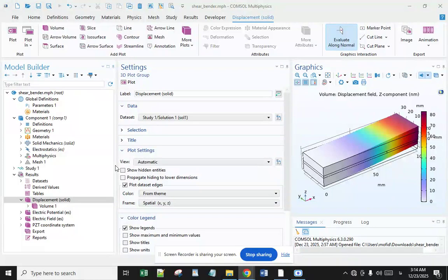It is clear from this table that the natural frequencies of the shear actuated beam are lower than those of the extension actuation one. This can be explained by the fact that the sandwich configuration is less rigid than the extension configuration because of the presence of the foam in the core. This difference increases with frequency because the foam becomes more deformed. It can be seen that in all three bending modes, the actuator's deformation is lower for the shear actuation mechanism.